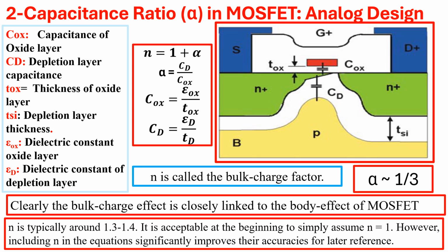Importance of capacitance ratio: a higher capacitance ratio indicates that the gate capacitance is significantly larger than the depletion capacitance, which can lead to faster switching time and improved device performance. Similarly, the capacitance ratio also affects the threshold voltage of the MOS. A higher C oxide relative to depletion capacitance can lower the threshold voltage, making the device more sensitive to gate voltage changes.